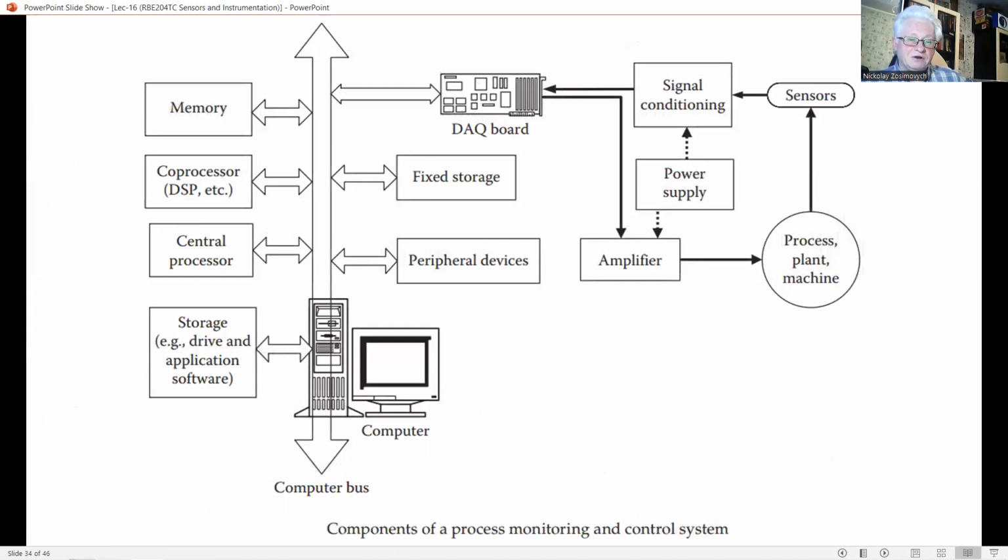An IC device called an analog to digital converter, ADC, is used to accomplish this. A feedback control scenario, which involves both DAC and ADC, is shown in this slide. Sampling an analog signal into a sequence of discrete values introduces aliasing distortion. This error can be reduced by increasing the sampling rate and also by using an anti-aliasing filter. Nevertheless, according to Shannon's sampling theorem, the frequency spectrum of the analog signal beyond half the sampling frequency, or Nyquist frequency, is completely lost due to the data sampling.